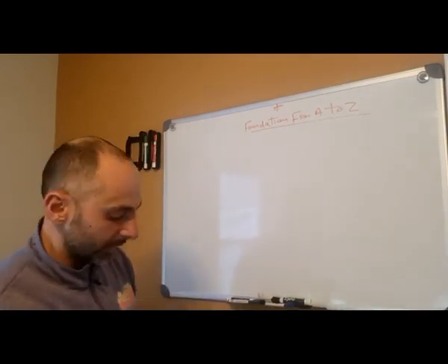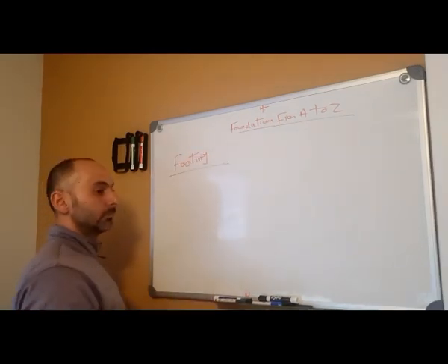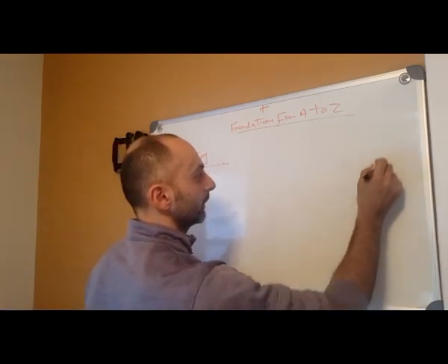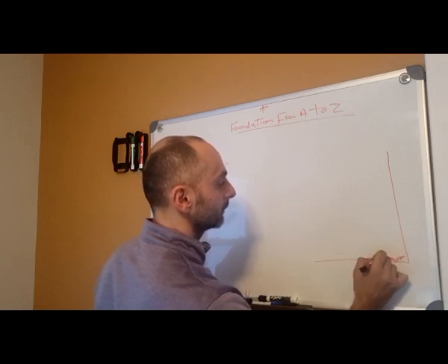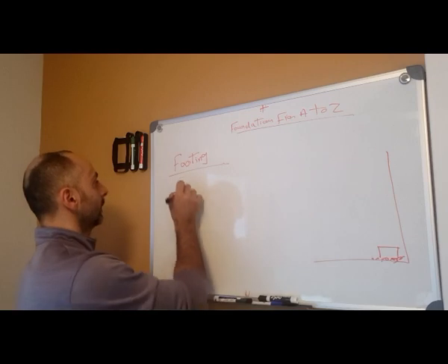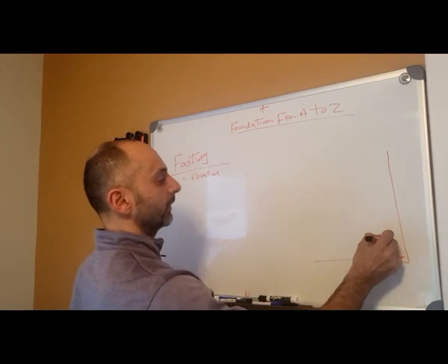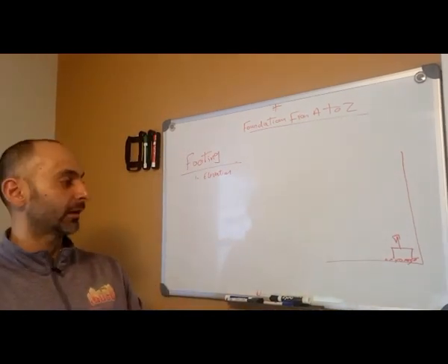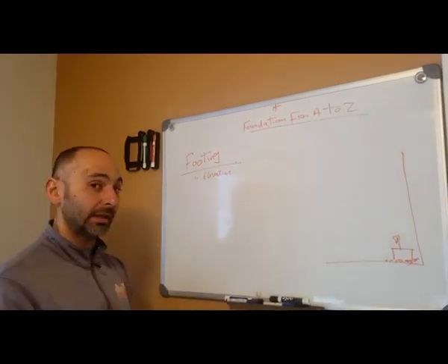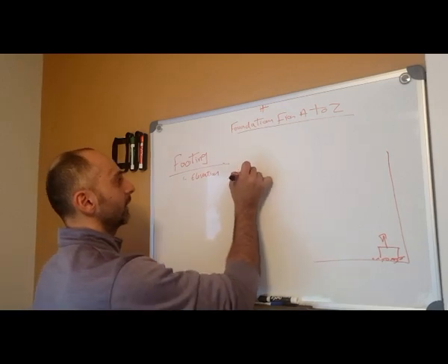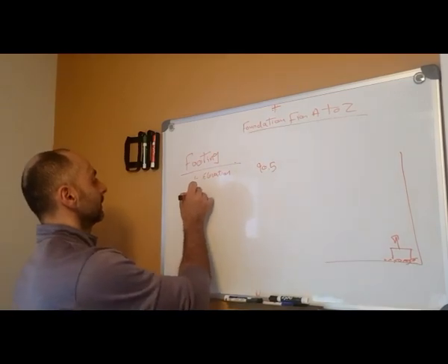Okay, footing, what do you look for? So you got your stone, here's your hole, you got your nice stone here, you got the form, and you're gonna look, number 1, elevation. Check the footing elevation with your contractor. If there's any mistake right now, you can fix it, it's not too late. So check the elevation again. You need to make sure you're at elevation 90.5 or 90.